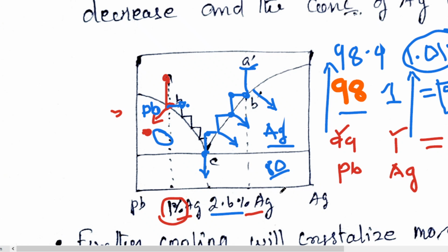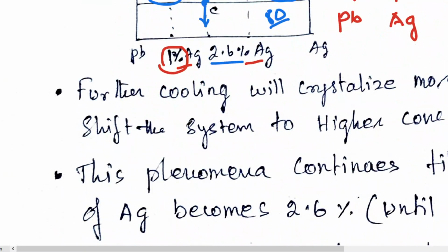Initially pure silver will get deposited, and when it reaches this composition, the eutectic composition, suddenly all the eutectic mixture will become solid, and that eutectic mixture we call an alloy. Okay, this is what it is. And if you take this composition, pure silver is deposited. Or here lead gets deposited in this area, and this process is called desilverization, that I have explained here.